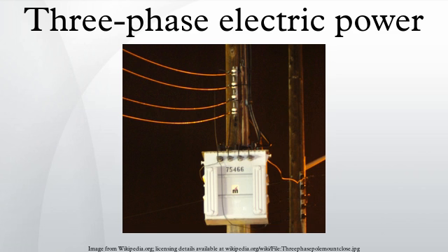Monocyclic power was a name for an asymmetrical modified two-phase power system used by General Electric around 1897, championed by Charles Proteus Steinmetz and L. Thompson. This system was devised to avoid patent infringement. In this system, a generator was wound with a full-voltage single-phase winding intended for lighting loads and with a small fraction winding that produced a voltage in quadrature with the main windings.